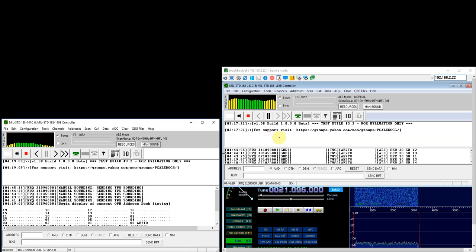So in the kind of scenario I'm talking about, each station would set up an SDR, perhaps something as modest as a Raspberry Pi, hooked to probably an SDRplay or some other software-defined radio, and then it would hop through the channel set using CAT control of the SDR. In this case it's 1 hop per second. You could configure it for 2 or even more hops per second.